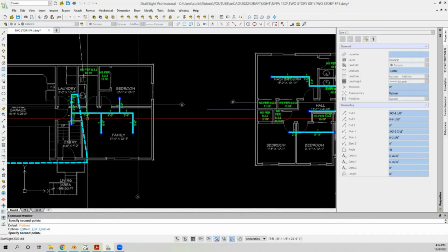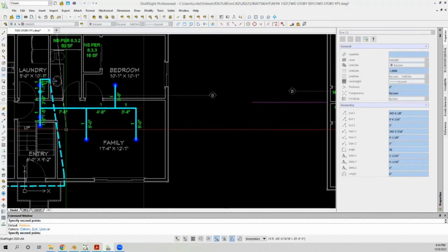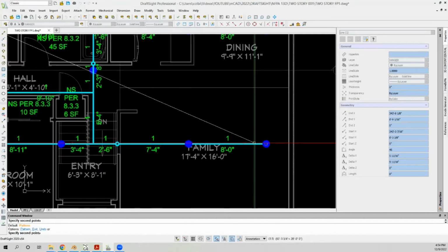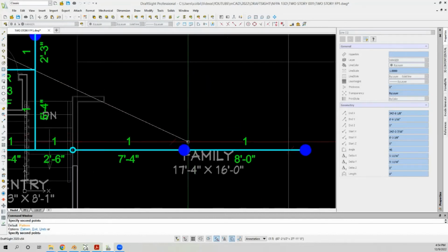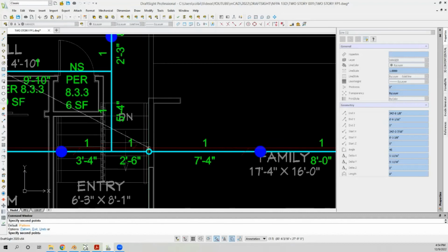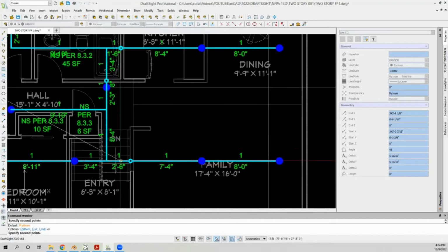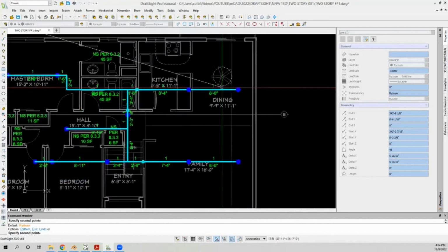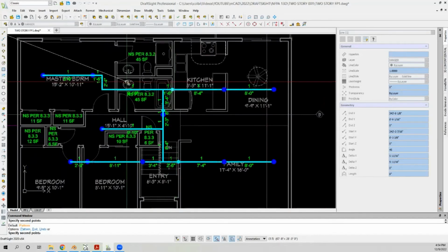We put our detail of what the hanger symbol is, and we just put these hash marks a foot away from every head and intersection of pipe, pretty much like you would be doing on Schedule 40 pipe.